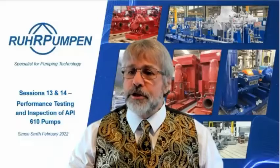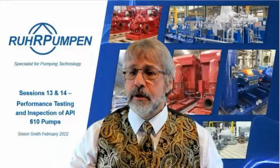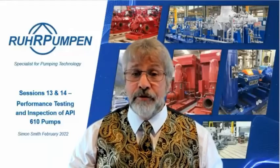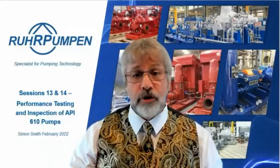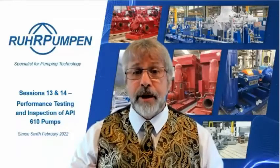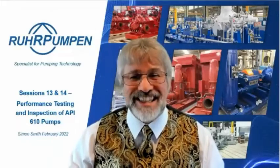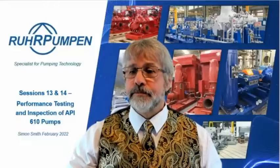What is the allowable deviation to evaluate the performance test? What is the remedy if this test fails? Means pump consuming higher power or not generating the head as required. Yeah. If the pump fails for any reason, you have to establish what the reason is and take the required action. It may be that it's a bad impeller, maybe a matter of trimming, maybe polishing. No, there's no easy answer. You'd have to do a root cause analysis, find out what was wrong, reassemble, retest.